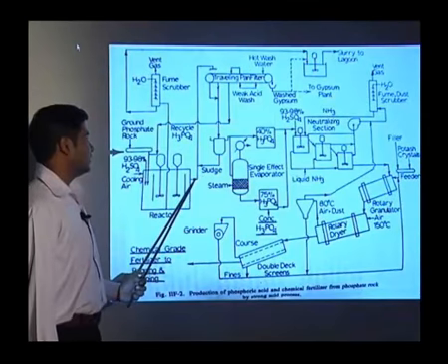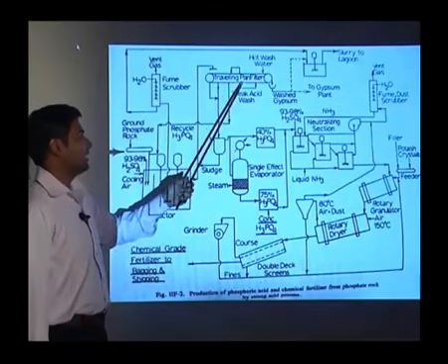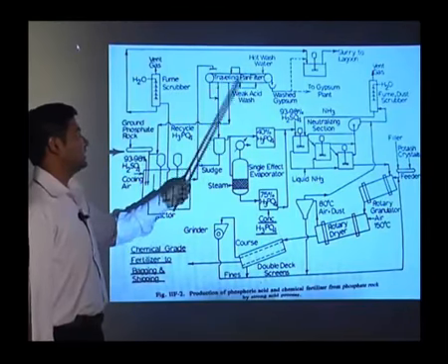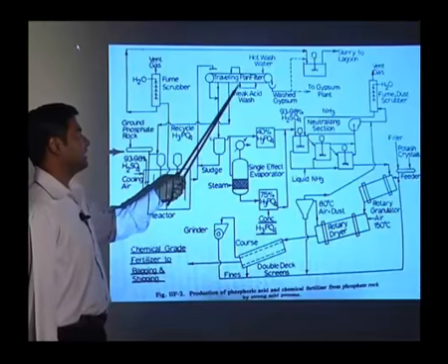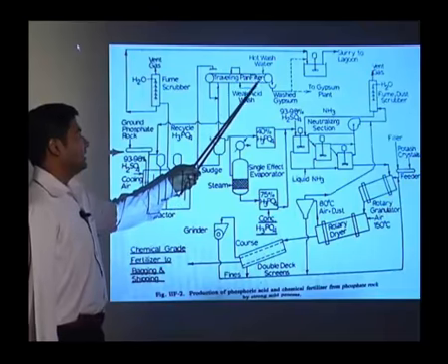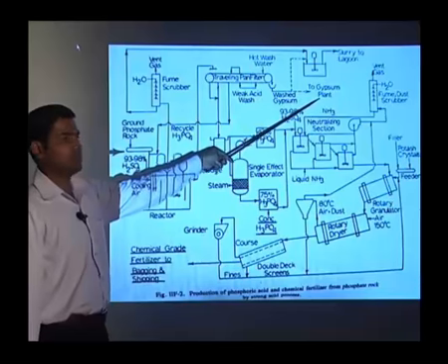We feed that to the traveling filter, where it will be washed, and the unreacted material can be sent back to the reactor. The filter will filter and the filtrate goes back to the reactor again. Then we get the washed gypsum, and the gypsum we can send to the cement industry.